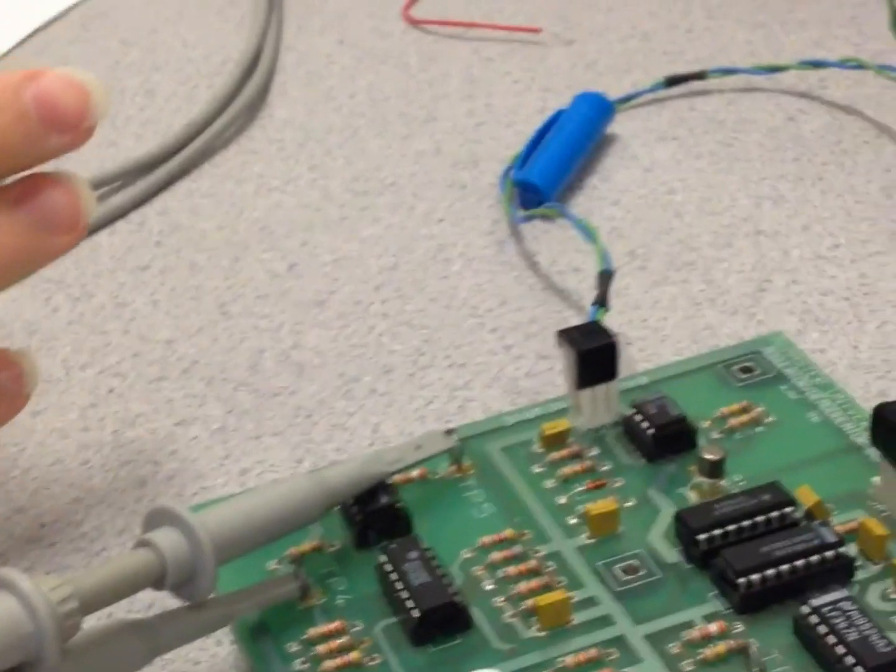But in this case, this is a practical filter. It is actually a weak practical filter. There are much better filters than this. But in the end, it will leak. It will give me 64 kilohertz components, 128 kilohertz components. These components are destroying my signal. If I want a better one, I must use a better Butterworth filter of much higher order to suppress these extra components which are destroying my signal or making it very noisy.